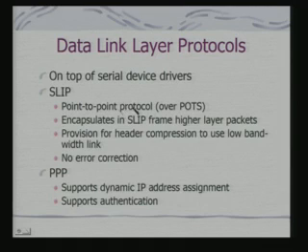So, when two systems are communicating over a standard telephonic communication line, SLIP can be used for connecting one computer to another computer via modem even. And typically for embedded systems, if it is provided with a serial port or a USB port, SLIP builds on the protocol for this kind of connectivity over any kind of serial port that is provided in the embedded appliance.